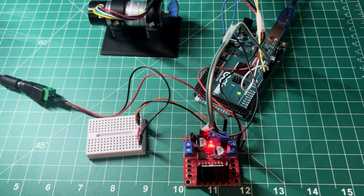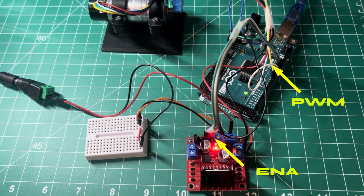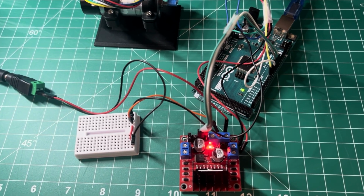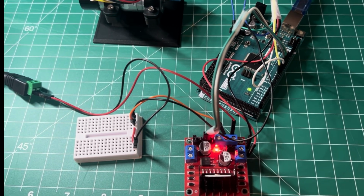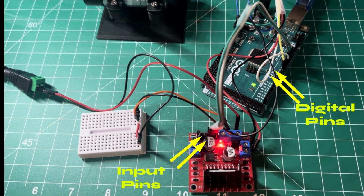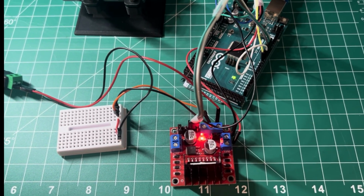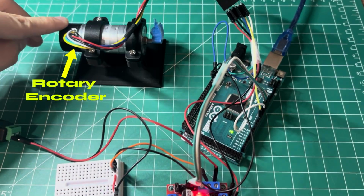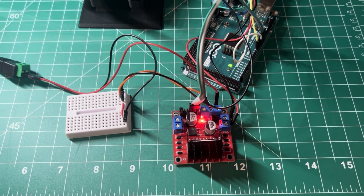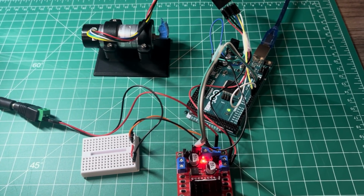The Arduino communicates with the bridge through 3 control pins: a power modulation pin that connects to the L298's enable pin, which controls the motor speed by providing the duty cycle. Also, 2 additional digital output pins connect to the L298's input pins, which determine the direction of rotation by setting them to high or low in opposite states. On the feedback side, the rotary encoder sends position information with 2 signal lines to ensure that the Arduino captures every pulse from the encoder without missing any steps, which is critical for accurate position tracking and closed-loop control.